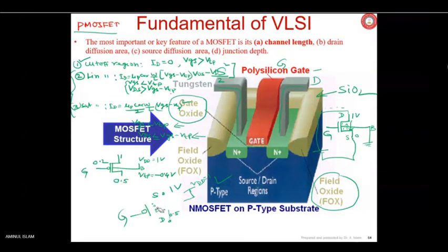Now, our question is in which region the MOSFET is operating. Tell me, if the source is at 1 volt, then in which region is it going to operate. VTP I have written as minus 0.4 volt. Now come up. Tell. Gate voltage I have given as 0.2 volt.